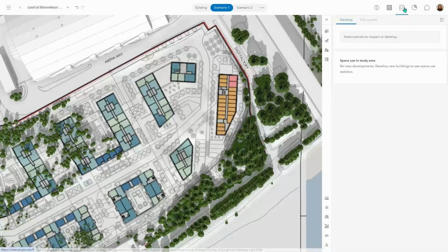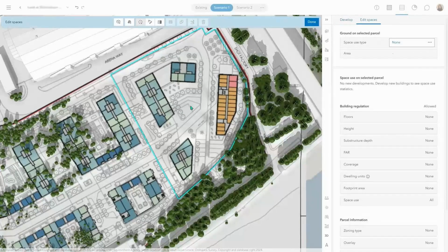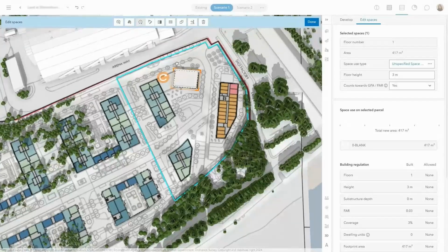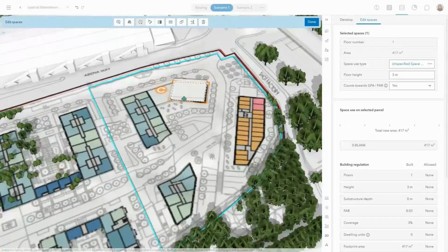could do this themselves. So what I'm going to do now is switch to the development tab, and start drawing my design based off my georeferenced image. I'll start by selecting my parcel and drawing my first building space. I'm drawing the foundational floor, and please note the digitizing guides to help me draw perpendicular lines. The built-in tools allow me to quickly duplicate the building space as well.